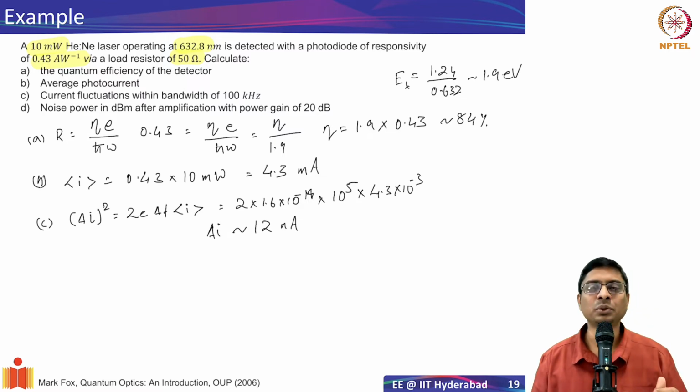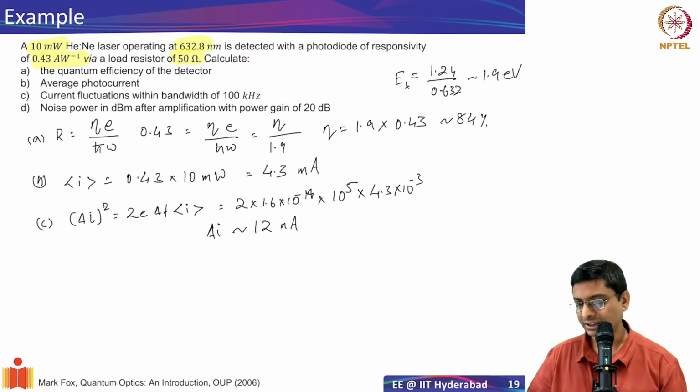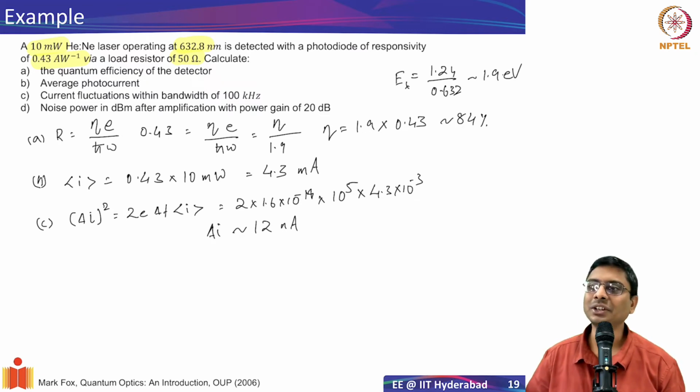If you go to extremely sensitive measurements, we use lock-in low noise amplifiers, which can have low pass and high pass filters set, so only in a certain frequency range you pass your input, and you can get much more sensitive detection. If you simply don't use anything, then you are getting all the noise from 0 to whatever the detector response is. We don't like that. Of course, if you reduce the frequency range, instead of 100 kilohertz I choose 10 kilohertz, my noise floor is going to reduce.